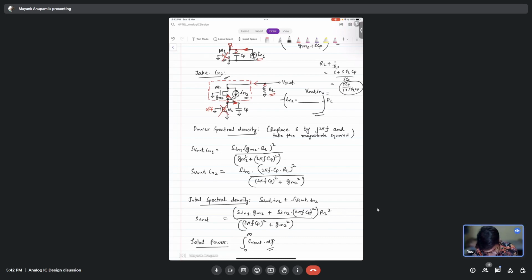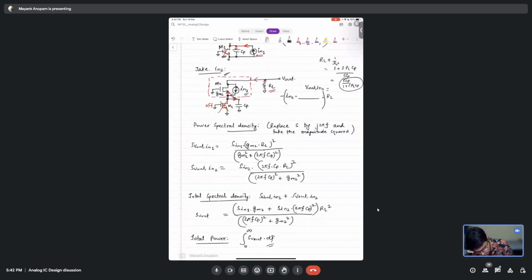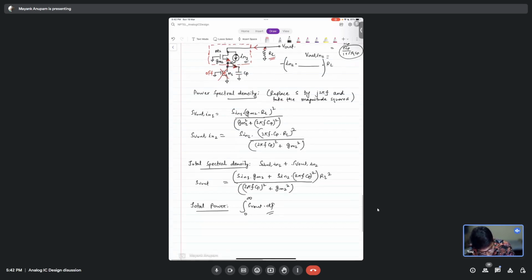But actually, sir, the equation was right. The person who asked me, you see that the current is definitely flowing in this manner, but we have assumed that this is ground. So when we assume that this is ground, what will the current flowing here be? We have explicitly put a ground here, right?